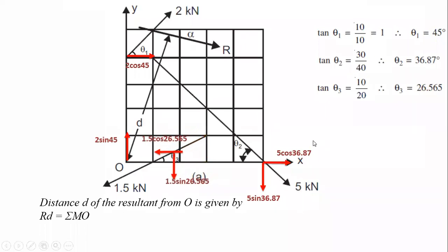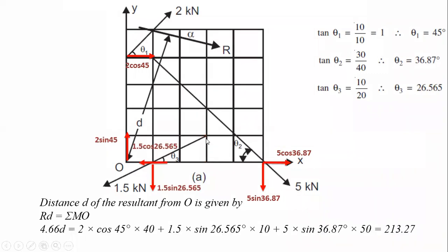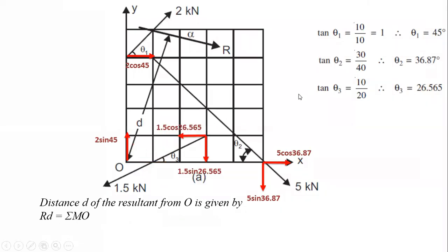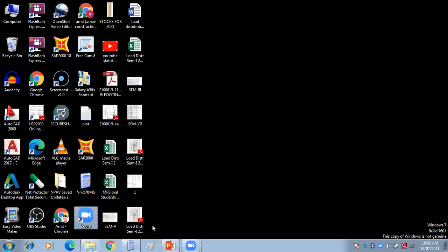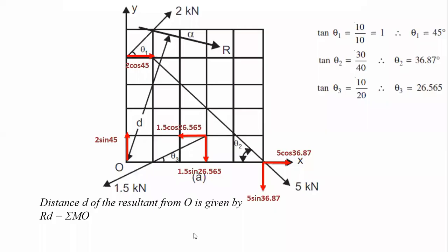Next one, this force. We may shift this force anywhere on the same line of action. If you check it out, this force makes a clockwise moment about point O. That's why this moment is positive due to this resolved force.